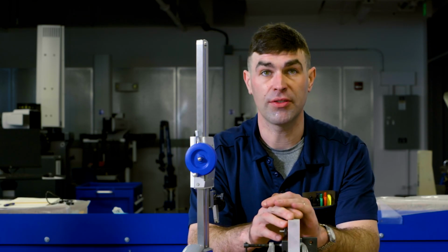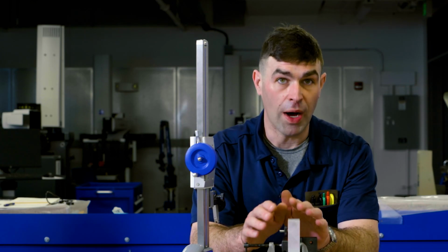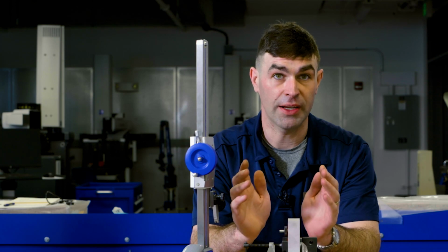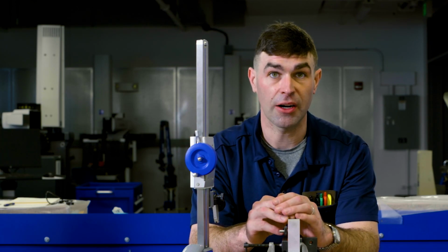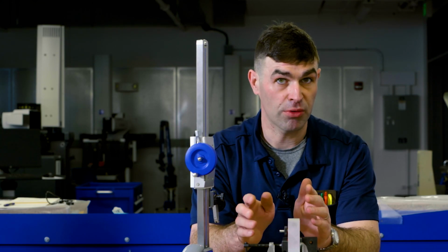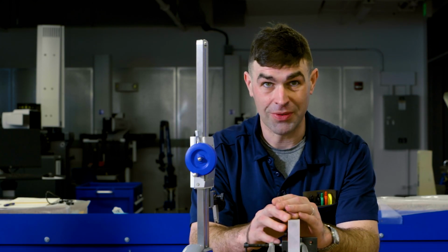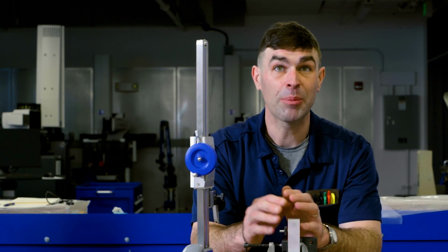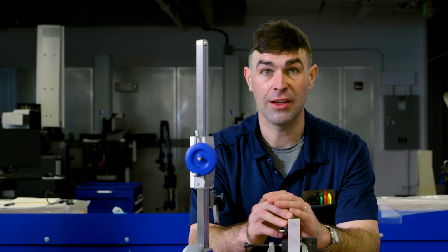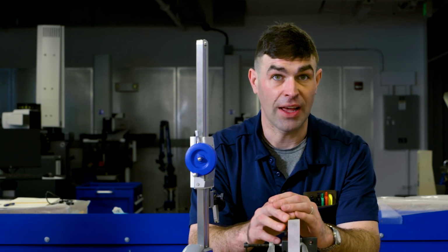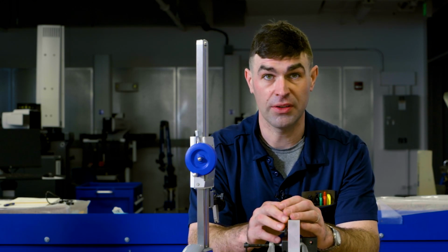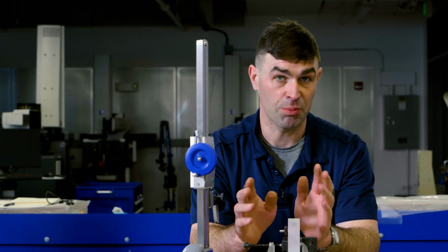And really the point of this video was just explaining why the pitch cylinder is the default. It's the true measure of what is going to happen when you thread something in there, whereas the minor diameter is not. The minor diameter can be very useful for measurement purposes. It's much easier to use a gauge pin, but you cannot assume that. It's got to be stated on the drawing, which is very easy to do. And I recommend if your design allows it, go for it. For non-critical situations, it would be good for a lot of things, much quicker to measure.